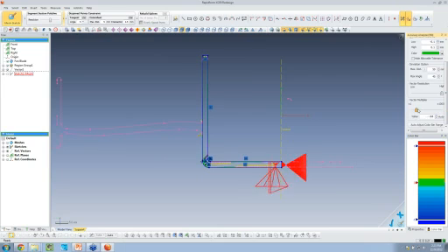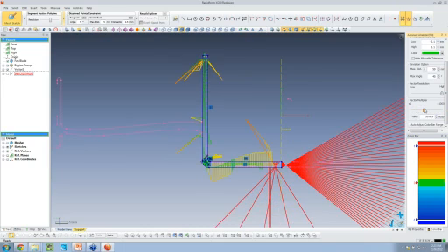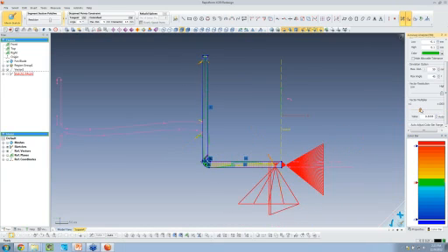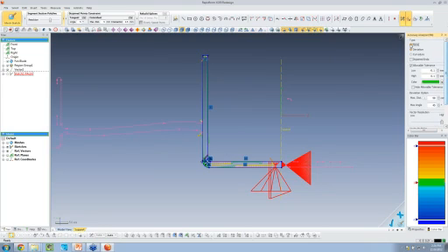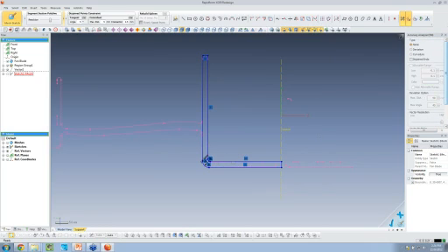I do a vector multiplier. You can see that, of course, at the ends I don't have anything. There's no scan data down there. But you can see in the areas where it matters, a little bit of a trend, so I can see what's going on here. But obviously, there's no scan data down here. So I'm about 40 microns off in this area. So I'm pretty good with that at 40 microns. And I'm happy. That could have been any features that you may have created.